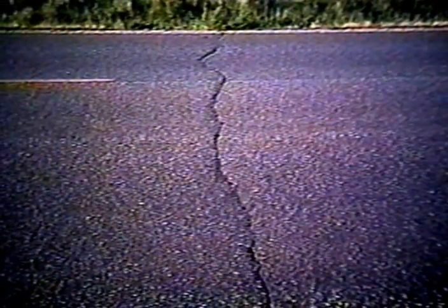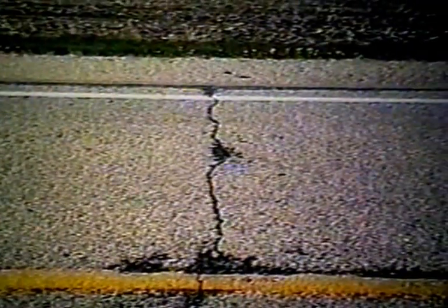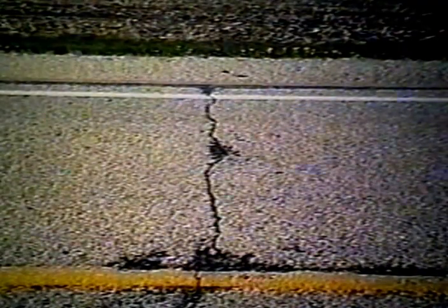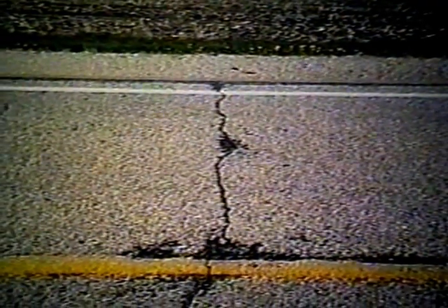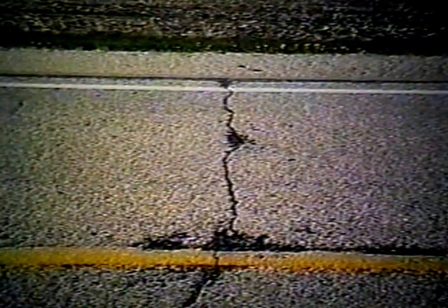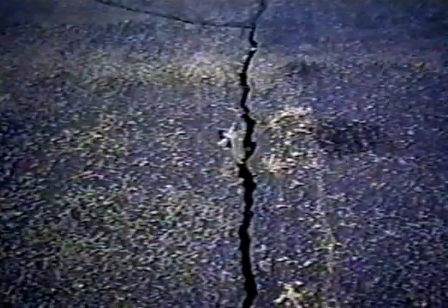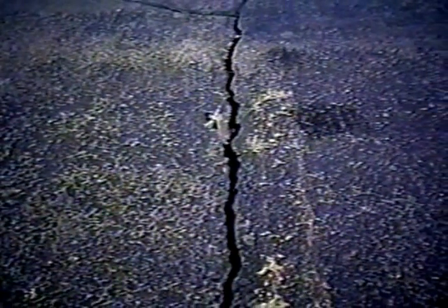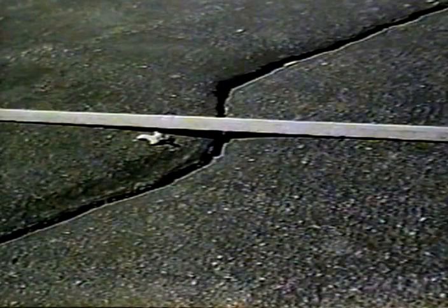When the crack initially develops, generally it's a hairline crack, fairly tight, but with time, as the pavement expands and contracts, the cracks tend to open up. That is, the pavement is not able to fully extend back in the summer and close itself up, so you see the crack begin to open up. Here it's maybe 1/4 of an inch, and with time they can open up. Here it's 1/2 to 3/4 of an inch. And here we have an example of a crack that's quite wide.